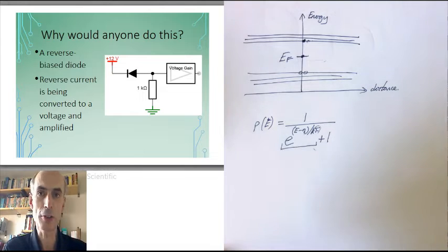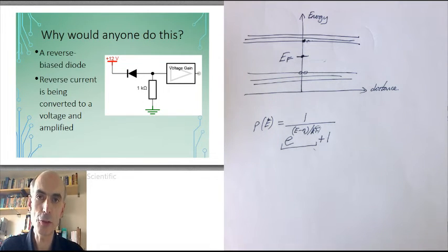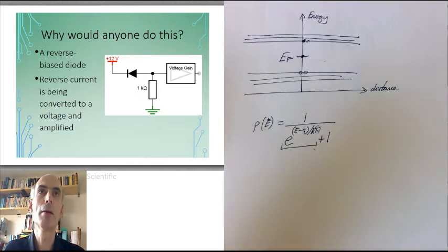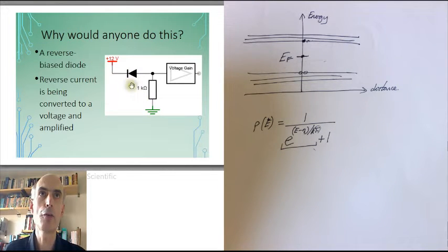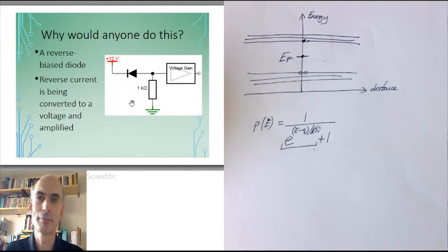So the saturation current turns out to be quite a strong function of temperature. In other words, build this circuit here, and you've built a thermometer, a temperature sensor. There are lots of ways of building temperature sensors out of electronic components, but this is one.